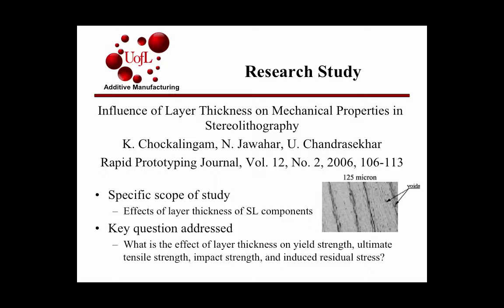During stereolithography, about 95 to 98% of the liquid resin solidifies. The other few percent actually causes lower strength and lower toughness in the parts. And that's why the SL parts go through a post-curing process. So the post-curing process is exposing the part to UV light, which improves the strength and toughness of the part. However, it can introduce shrinkage and residual stresses.